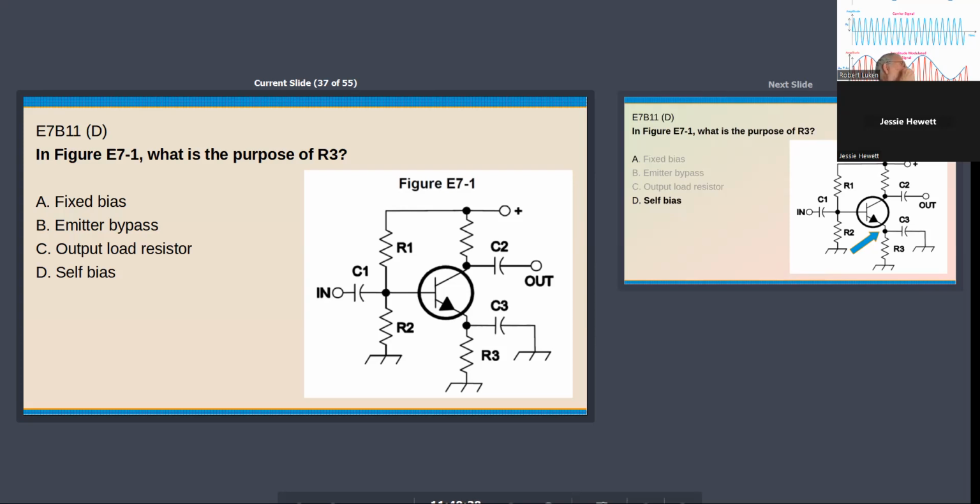It's somewhere between cutoff and saturation, right? If you had it set up for say 10 milliamps total, depending on your unknown load resistor, then you'd want to bias it like 5 milliamps. So whatever the base current is to provide 5 milliamps on the collector-emitter. So then the transistor is conducting to some degree, wherever you chose that, so you do have a voltage across R3, you have a divided voltage in between R1 and R2. That allows it to be biased on or off, and somewhere in between, so there are variations of conduction in the transistor.